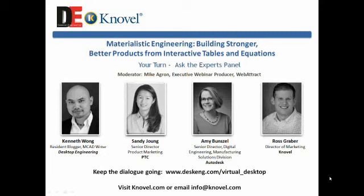Thank you. I wanted to answer Amy as well, because there's another aspect of this that we found interesting. Now that we've got our mold flow product hooked up to our stress analysis product, you're able to actually get the as-manufactured material model out of the plastic injection molding simulation and use that to do your stress analysis. So rather than looking at a uniform material, because a plastic will change as you melt it and mold it, you can actually understand the as-manufactured simulation. So that gets you a little bit closer to not needing as many physical prototypes.